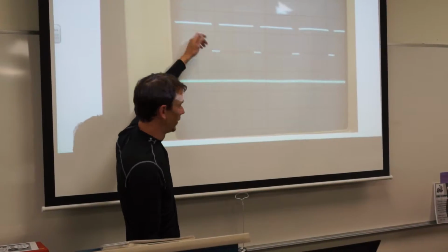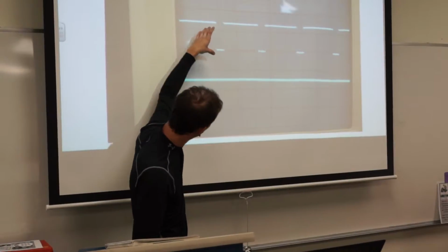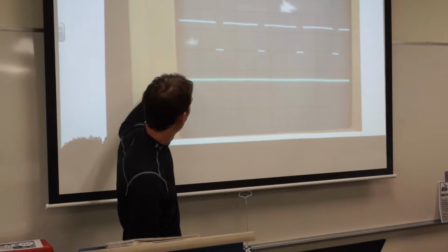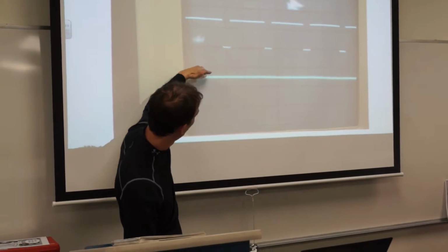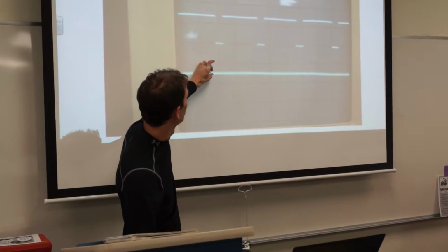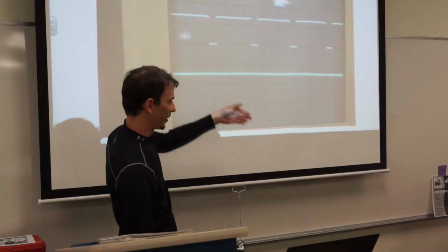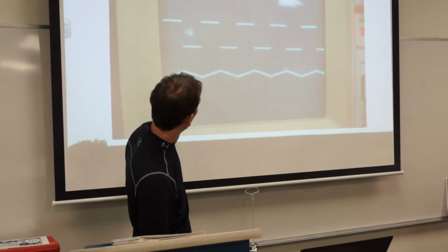So I would say, I forget exactly what duty cycle I was at, but this is probably around 80% duty cycle. And you can see it's putting out a pretty clean noise line on there. There is some much smaller deviation. If I had better focus on the O-scope, you can see the smaller minute amounts of noise going in there. But if you step back to the other picture, this is what I was considering our worst case.